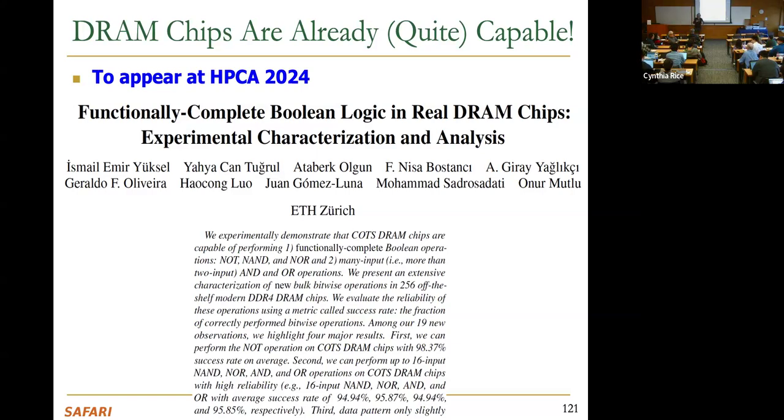First of all, in general, they're not open to these ideas. For example, let's pretend they are. So basically, I would start with RowClone, right? RowClone is a very simple operation. I think a lot of these things are chicken and egg problems, right? If you don't have this in hardware, software people will not build the infrastructure to use it. I would start with very simple operations like copy support in DRAM. Very simple one, like fix the granularity to a row granularity, put it out, let people develop software, and hopefully get benefits. And over time, I think that cycle will hopefully be broken. That would be my recommendation to them.